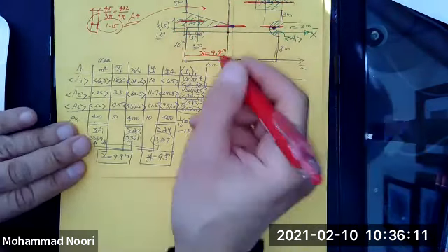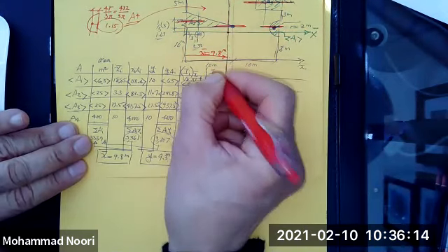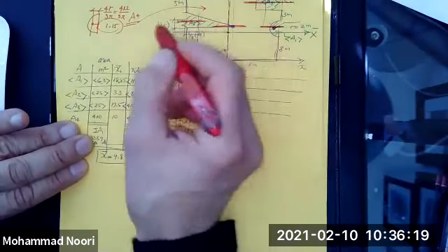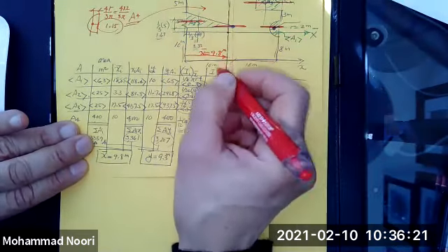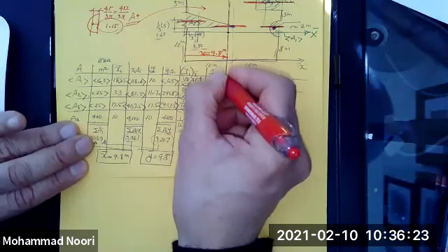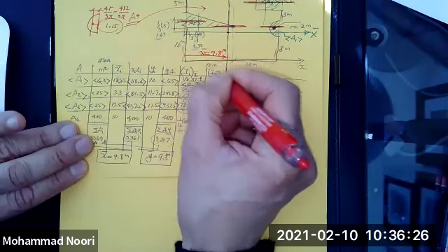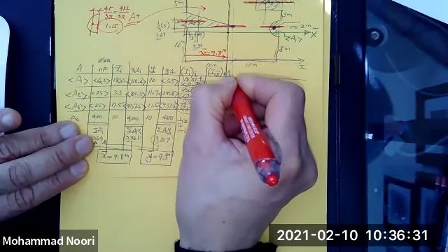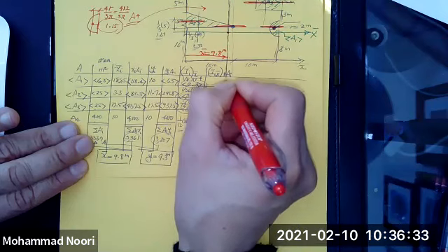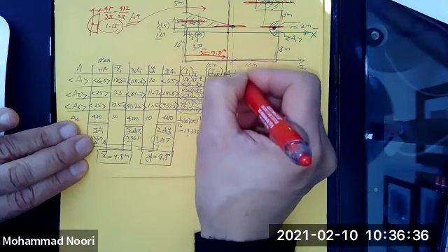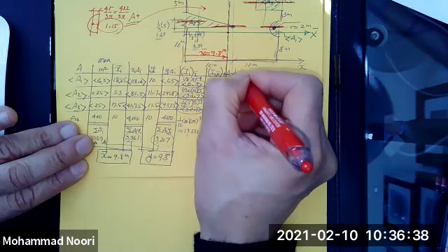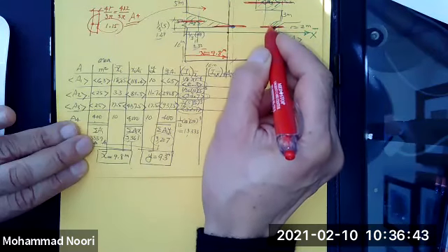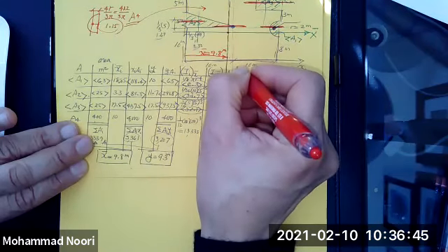What does that mean? This is a parallel axis. This axis is parallel to the central axis of each shape. So you need to add the moment of inertia of each shape about its own central axis, add to it the area of the shape times the distance from that central axis to the corresponding central axis of each shape, squared.